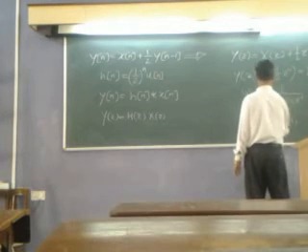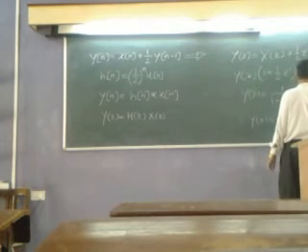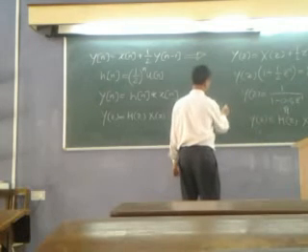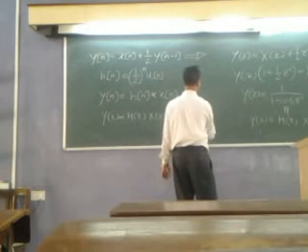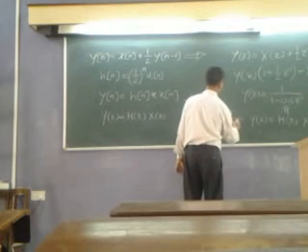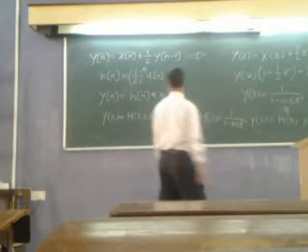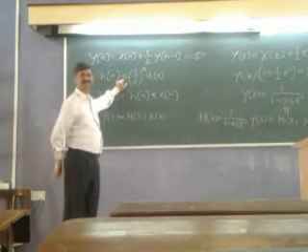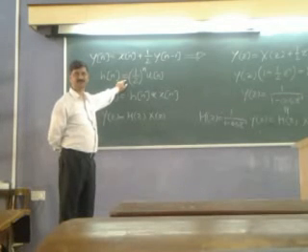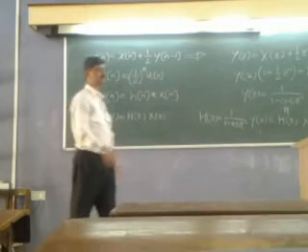We know that yz is equal to xz into hz, where hz is 1 upon 1 minus 0.5 z inverse. This also we can find from half raised to n un, we know that the answer is 1 upon 1 minus half or 0.5 z inverse. So we find that the thing matches.